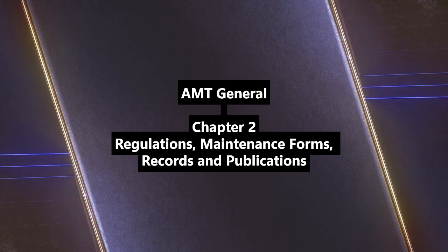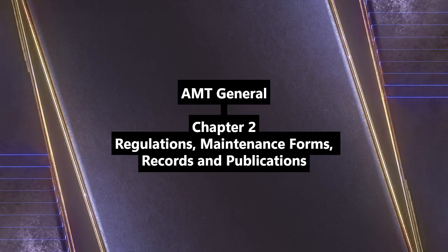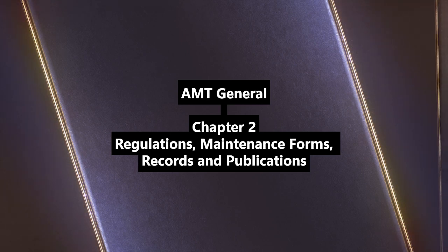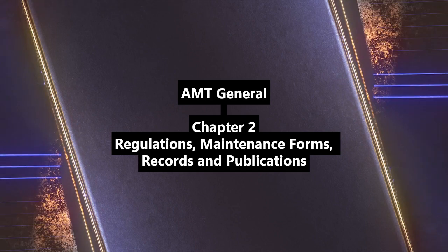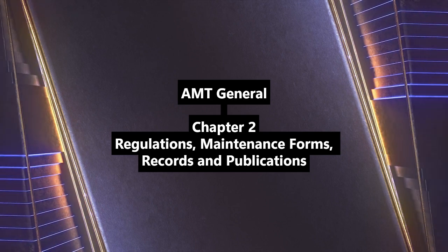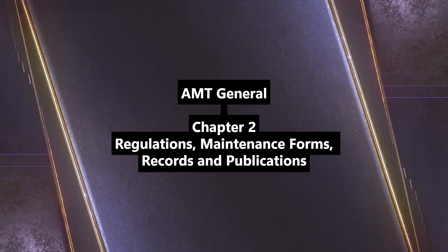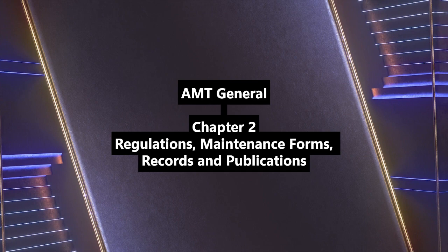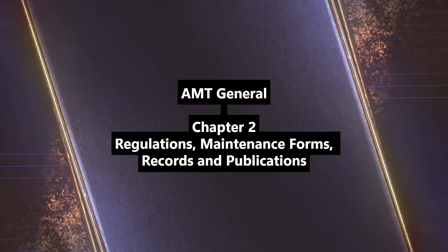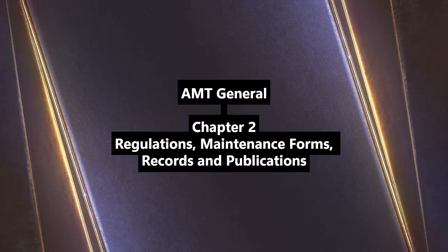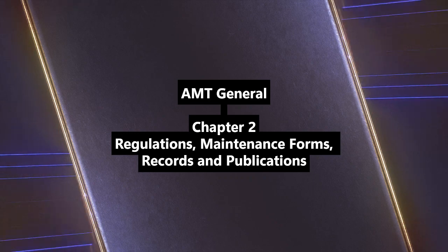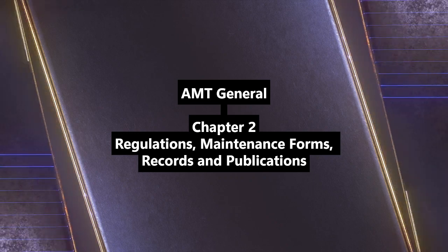Okay. What about certifying the people doing the maintenance? That's primarily 14 CFR Part 65, certification: airmen other than flight crew members, while Part 61 is for pilots. Part 65 covers ATC operators, dispatchers, mechanics, repairmen, parachute riggers. A whole range of non-flying roles. Exactly. And our source mentions Chapter 15 goes into more detail specifically on mechanic certification. We'll keep an eye out for that.